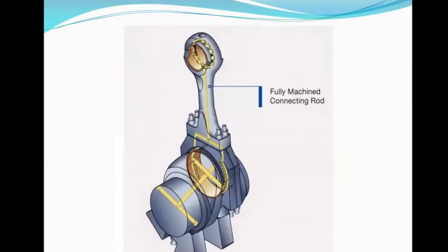So in semi pressure, the connecting rod has a small end and a big end. A hole is provided in the machined connecting rod so the lubrication will reach different parts. From that, pressurized oil will be supplied. Inside the circular periphery, oil is also supplied through the hole. So this is the inside mechanism of the connecting rod.